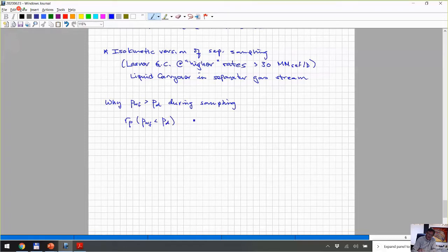In a testing period, it may be that you're creating this steady state region 1 during the testing. So while you're building this mobile oil saturation in the near well region, and even if you've already built it, the producing oil gas ratio will be approximately equal to the solution oil gas ratio at P star. And this very well could be less than the initial Rs.